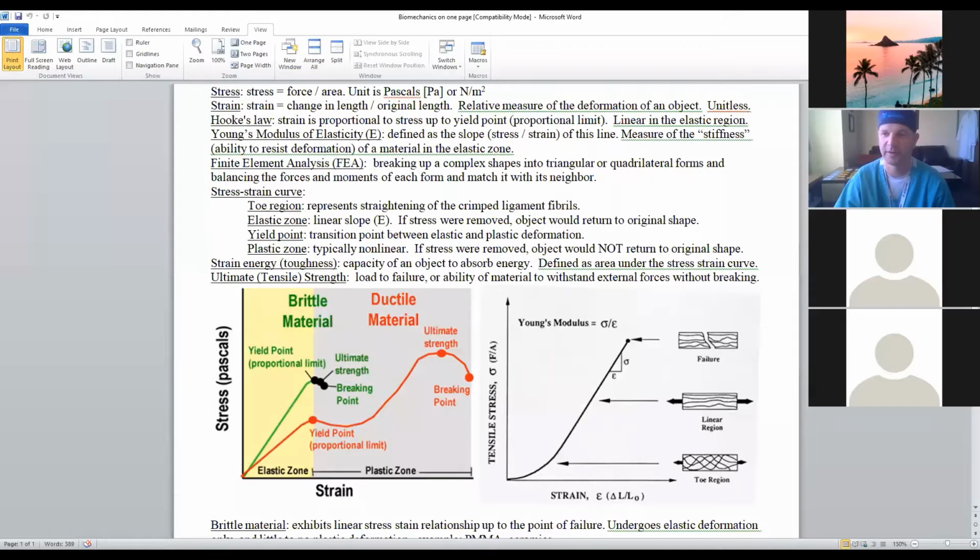Oh, sorry. Somebody else? Ceramics? Yep, ceramics is one. And there's another one that they typically say. PMMA? Yep. Those are things that basically shatter. If you think of something brittle, like dropping a plate on the floor, anything ceramic or made out of glass is a brittle material. That's in contrast to a ductile material, which is most metals. If I take a metal knife, I can bend it and let it go, and it would stay bent after it reached the yield point.